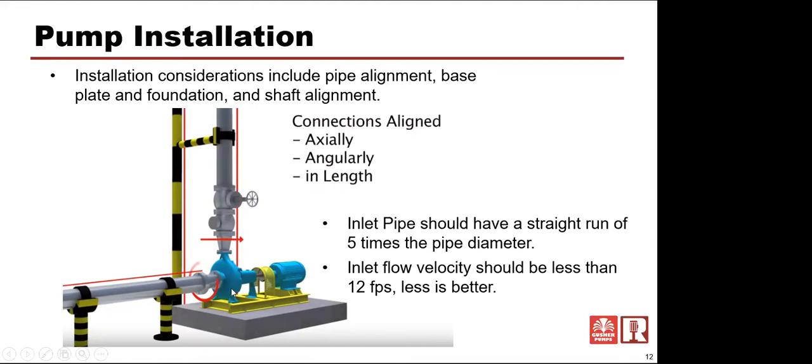In other words, as these vanes are coming around, they're not going to be evenly filled because of that elbow right in front of the pump. And therefore, you're going to throw an imbalance on this whole shaft and this whole pump as it's trying to pump. It's doing more work on one side of the impeller than it is on the other.